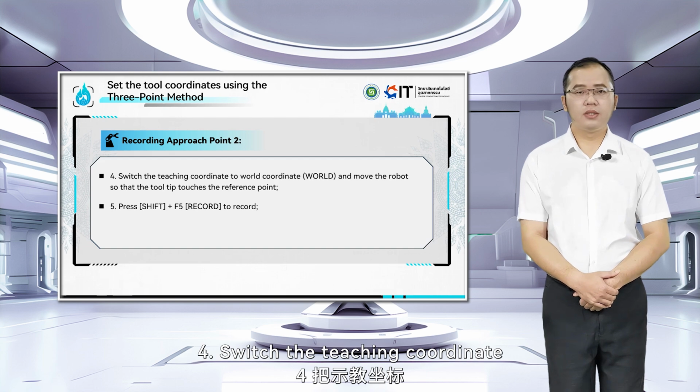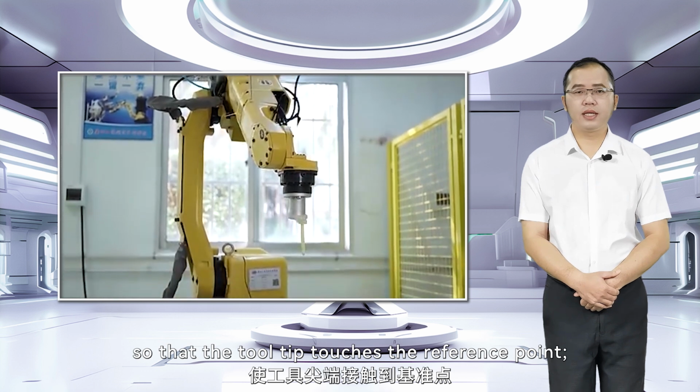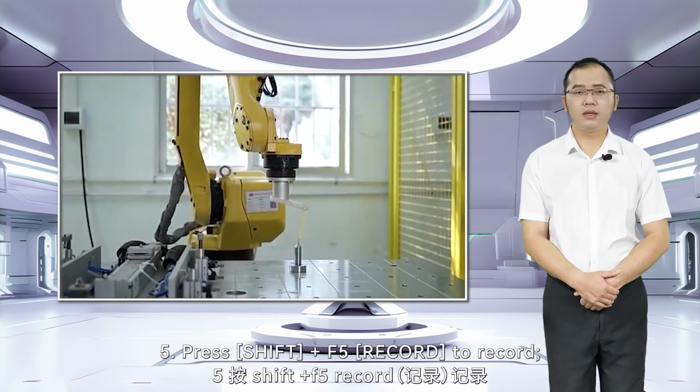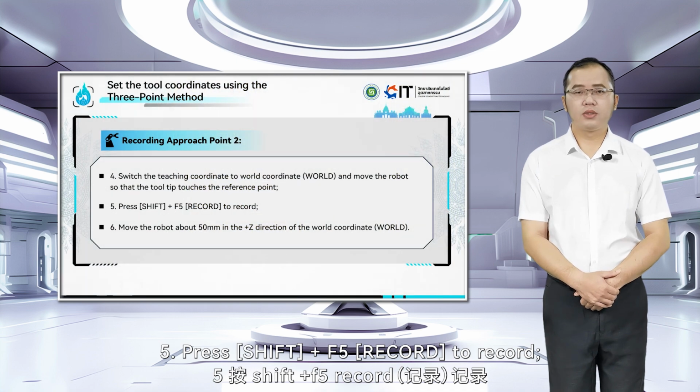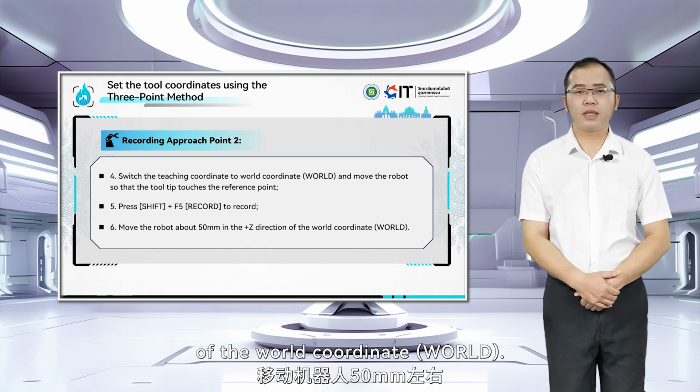Switch the teaching coordinate to world coordinate, world, and move the robot so that the tool tip touches the reference point. 5. Press Shift plus F5, Record, to record. 6. Move the robot about 50 mm in the plus Z direction of the world coordinate, world.